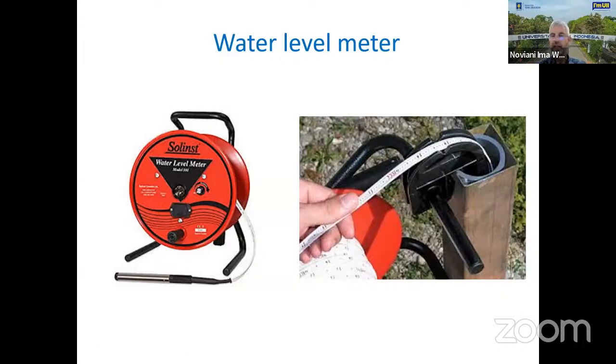All right. And then as the pump test continues, the water level is dropping. You lower the logger a little bit more, and still it starts beeping again. Then you look at your stopwatch and say, okay, 5 minutes later, the next reading is 2.95 meters. So we basically have 10 centimeters difference compared to the first reading. So you do this then every hour for 12 hours, 24 hours, even longer.